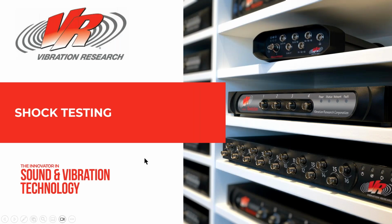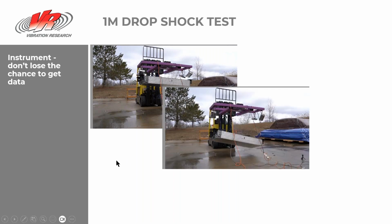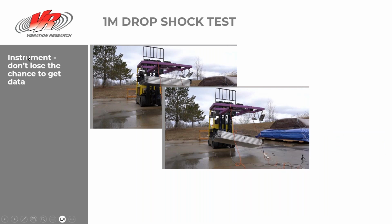Okay, I just thought I'd cover shock testing now. This is just a 1 meter drop, a typical safety drop of what might happen on a battery pack, instrumented up with accelerometers inside and it landing. My one thing here: I've done a lot of drop tests on explosives, and it's very difficult to get clean drops. And obviously you'll see from this one here, this particular drop did not land flat as you might expect, so all of the damage was in that corner there.